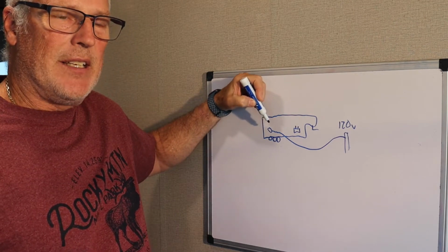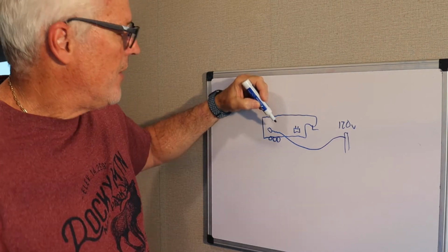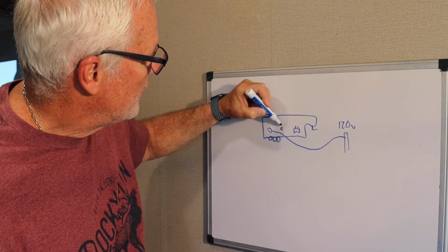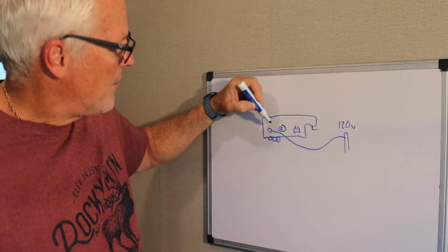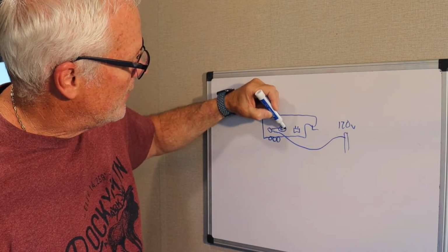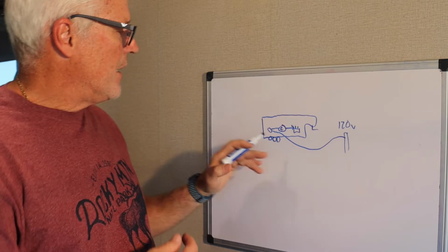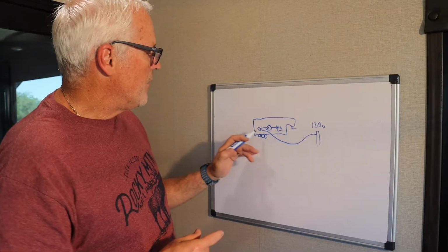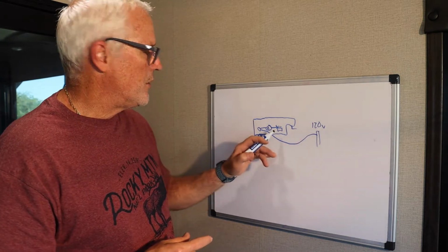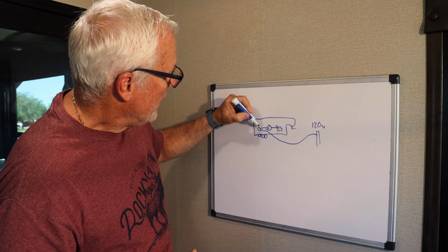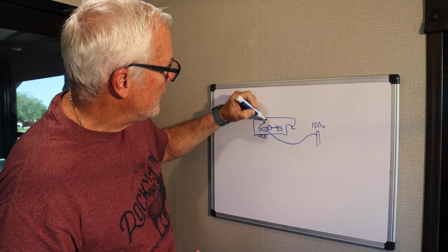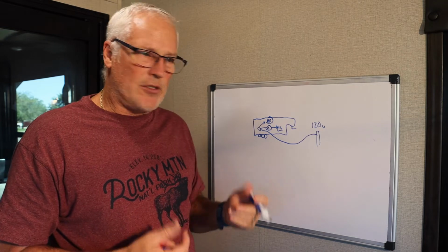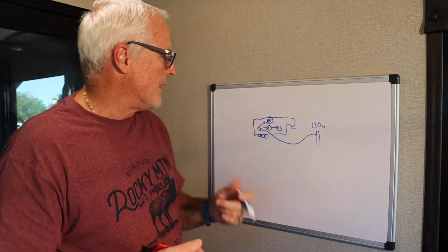We talked a little about inverters earlier. This is also a concept of a converter. So this is my converter. Some of this power is actually going to go through a converter into my battery. A converter changes 120 volts to 12 volts. So now we can use some of this 120 volts to recharge our battery. And the rest of it will come out here to supply power to our AC circuits. And again, the AC circuits are like your plugs in the wall, things you would plug in.